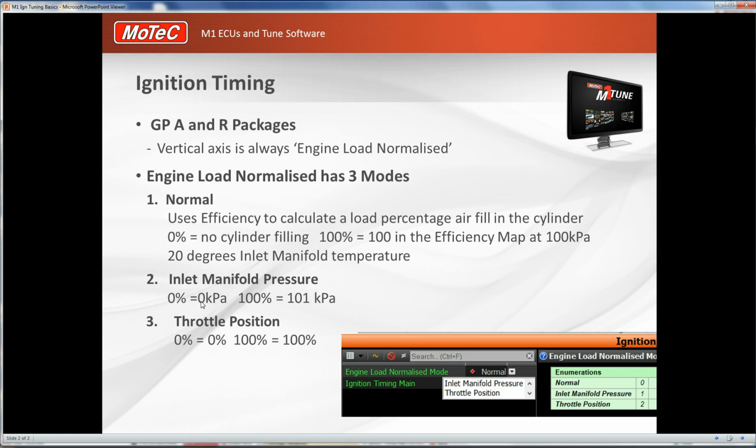So you can pick a couple of points, get the ignition timing right at those, and if you can't, for instance, get to a couple of points on the map at this particular test, your consistent linear interpolation should predict what the ignition timing would be for a given engine load, or measured engine load, or calculated engine load on the engine.